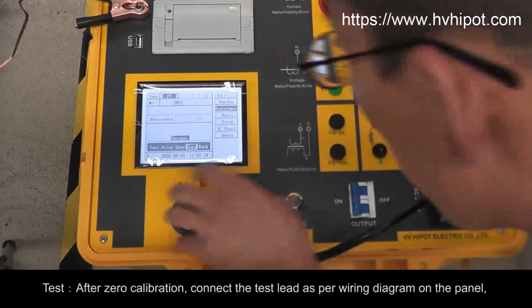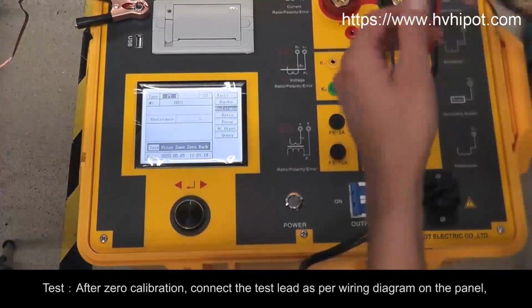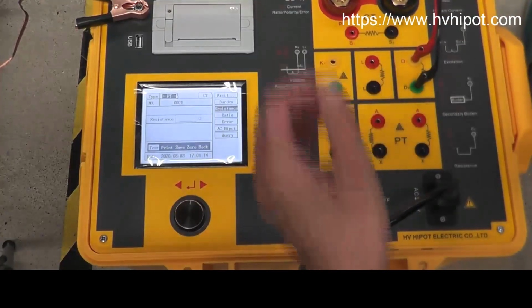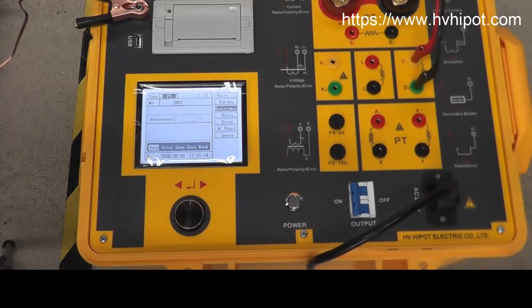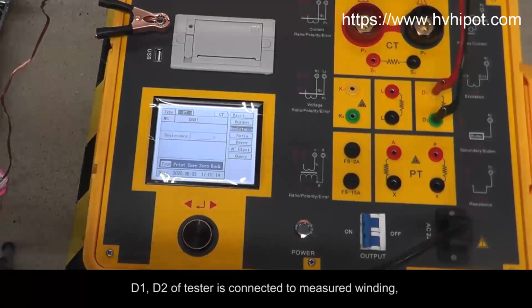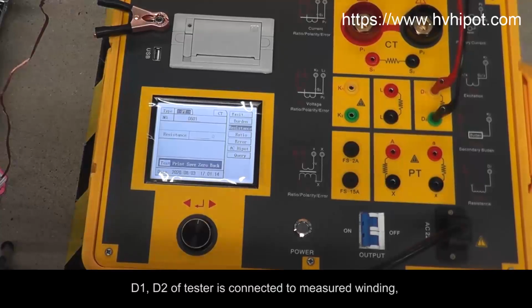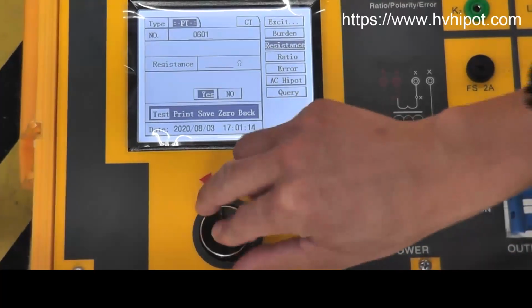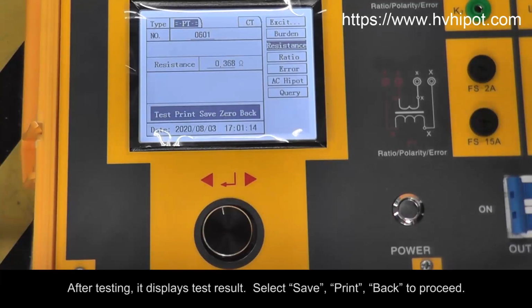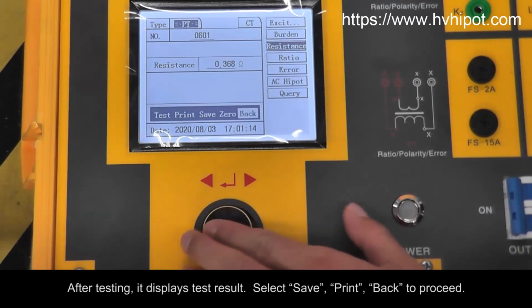Test. After zero calibration, connect the test lead as per wiring diagram on the panel. D1, D2 of tester is connected to measured winding. Select Test to start testing. After testing, it displays test result. Select Save Print, back to proceed.